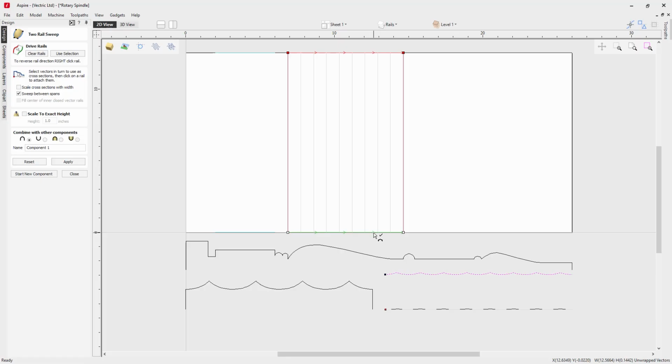Pay attention to my mouse. As I hover it over to the left, eventually it's going to pick up on that midpoint just there. You can see the difference on my mouse pointer: to the right of it is a check mark, and underneath it a node appears. So that's telling me it knows that node is there, and that is why we moved the node earlier, so we can click on that, and that's where we can place our larger octagonal shape profile.